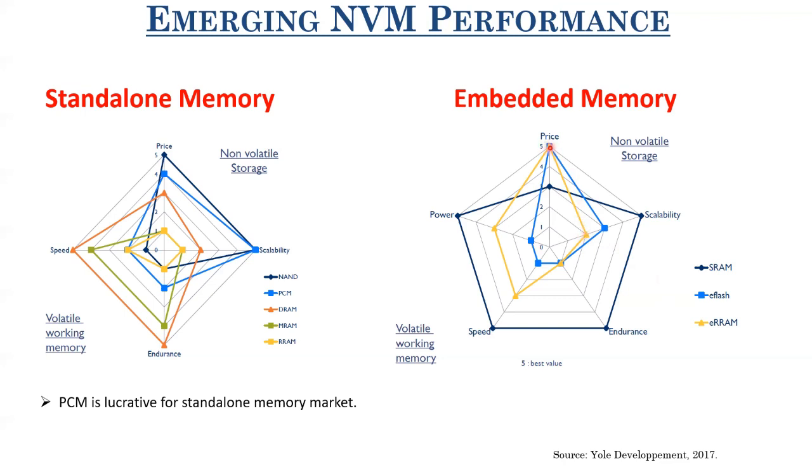In terms of price, it's really cheap as compared to your SRAM because here density is even larger, right? Also, in terms of power, it is actually less power consuming as compared to embedded NOR flash. However, it is more power consuming as compared to your SRAM. Why so? Because in SRAM, the leakage power dissipation is there, but in RRAMs, the conductance range or resistance range is limited, and corresponding to R_OFF, which is in some gigaohms at max, you'll have some nanoamps of current flowing. So even that way, it's less power efficient as compared to your SRAM devices.